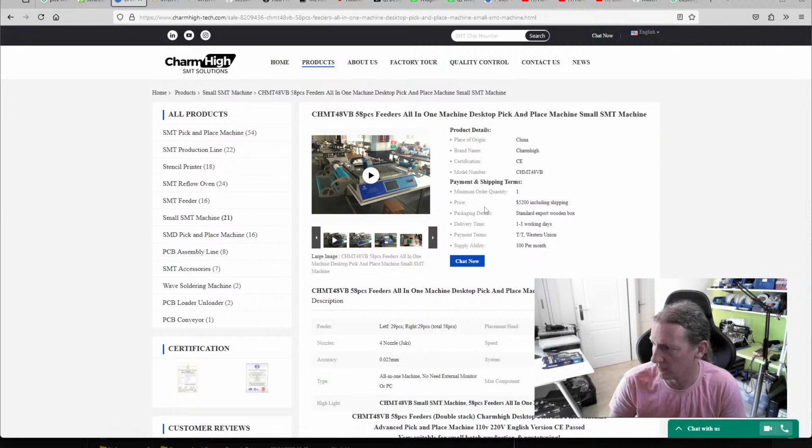Some of the sweet spots for me involved reusing lots of components on a few varieties or different boards, such as making 3 flight controllers of various different sizes for various different applications which have a common set of parts. And if I was to order from a factory like 500 of one, 500 of another, 500 of another, that's a massive outlay. And if there's problems with any one of those designs and it fails, then you've got loads of stock on hand and you've got parts that you can't use and it's too risky.